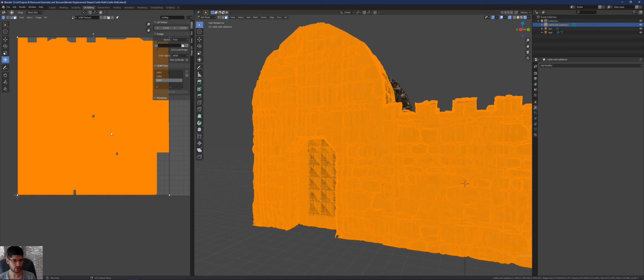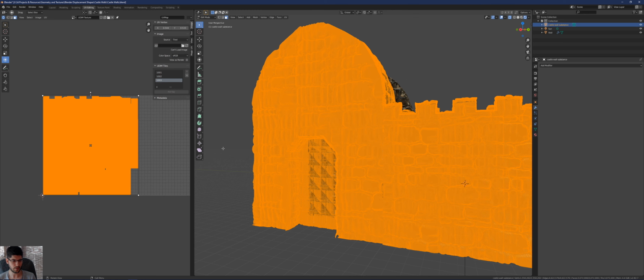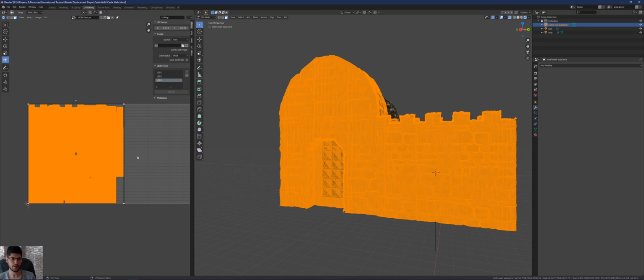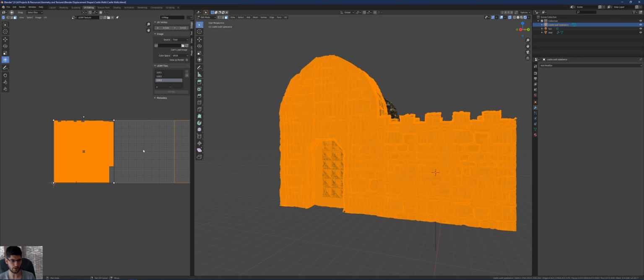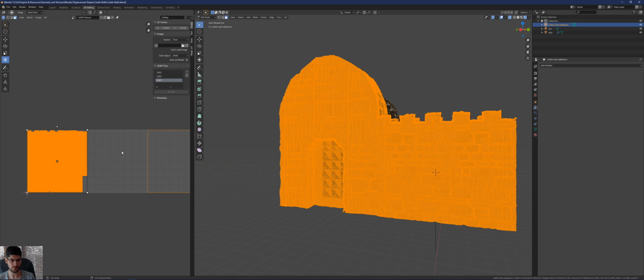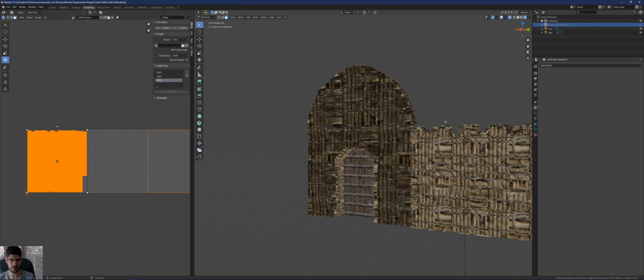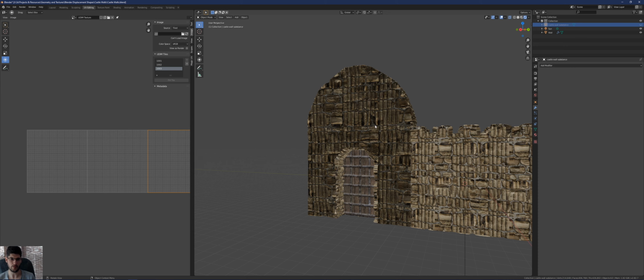They're in the same setup as we laid them out to begin with, but unfortunately they're all lying on top of one another, so we can't pull them out and put them into their respective UDIM tiles. If we put the textures back in now, they're just going to overlap too much. That's why currently we don't have the option to export the mesh from Substance Painter and use it as we want to in Blender.